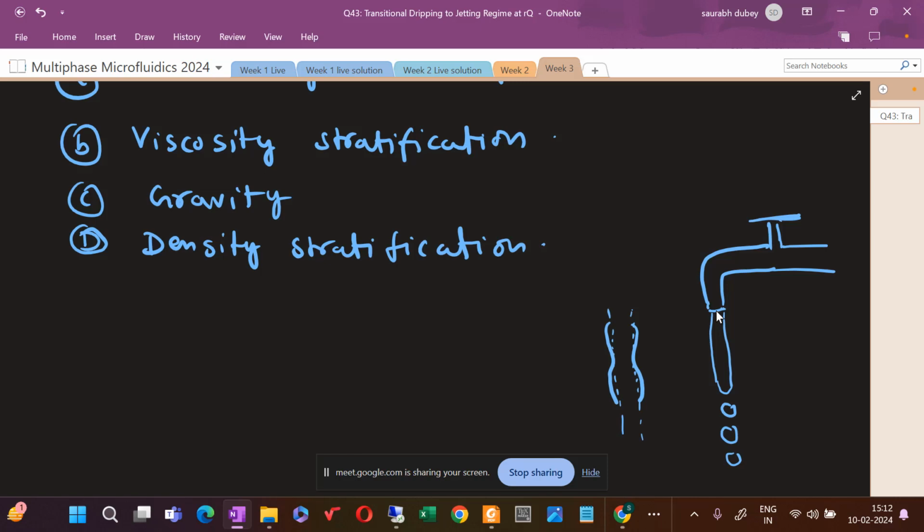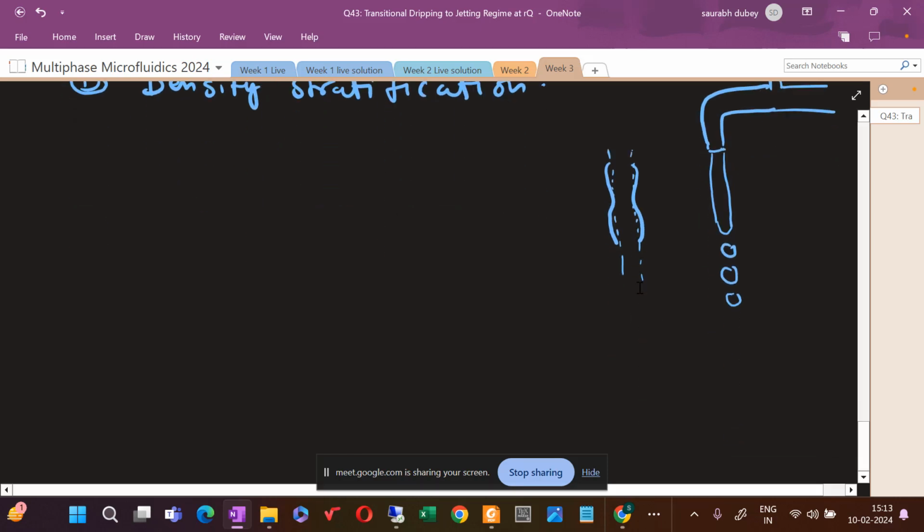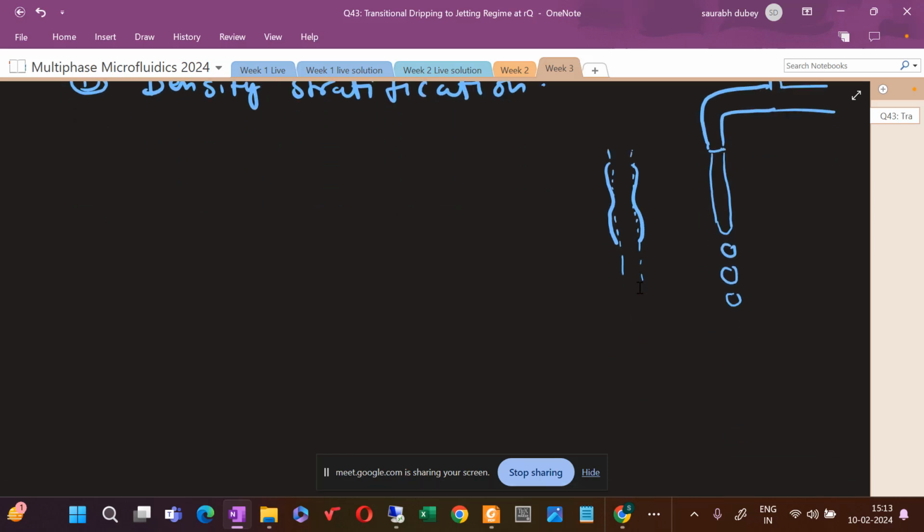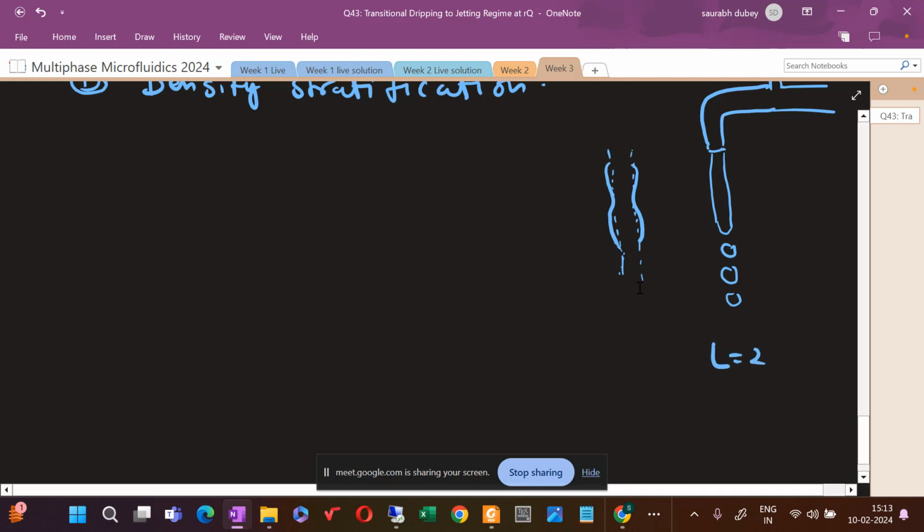and that gradually leads to the breakage of the jet. So at what particular wavelength will this breakage happen? If you dig deeper into this subject, you will come to know that if the length is 2 root 2 times the diameter of the jet, then there will be breaking, the condition for breaking.